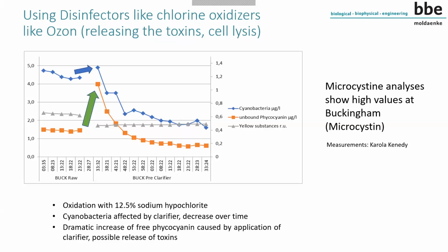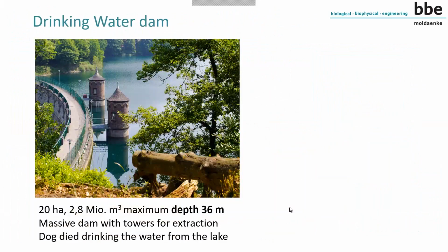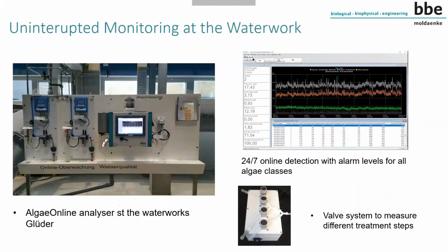Okay. And for the AOA, it's a matter of the sampling. This is my own question. For the AOA, it's a very special case. The AOA uses a peristaltic pump, which pumps the water inside the instrument. From the theoretical value, it can be 10 meters, but you have to imagine there is a delay between the intake of the sample until it enters the instrument. So usually I think it should not be much more than 2-3 meters.